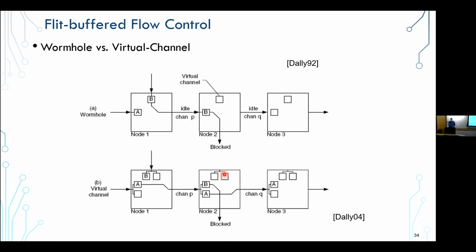And the reason for all this is that you don't want to lose these flits. If you lose flits along the way, there is another layer of the network that you have to add that takes this into account and resends either the flit, or the overall packet or message, right? And that ends up increasing the latency significantly. In these types of networks, which are really memory semantic networks, you want to get as quickly as possible to fetch a word or a cache line somewhere across the chip,